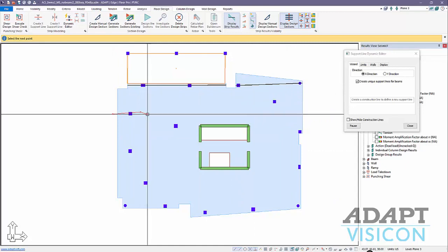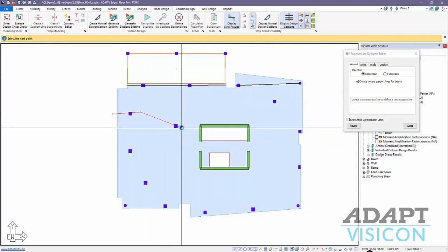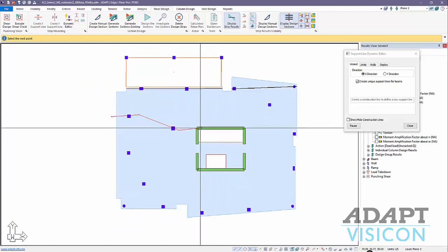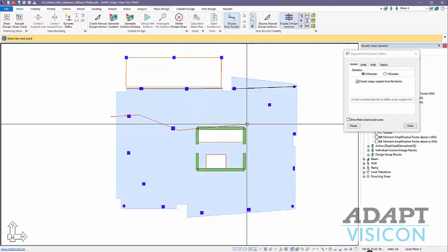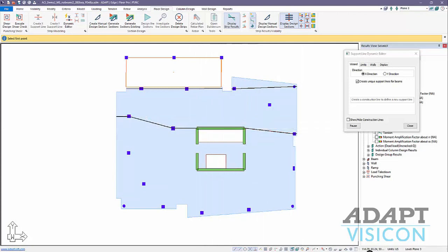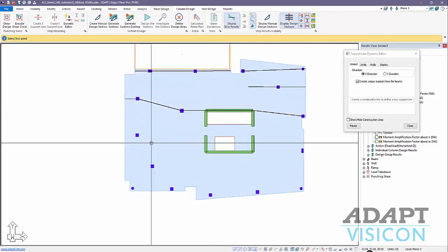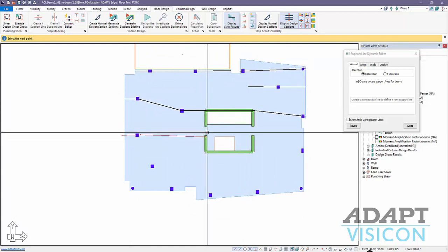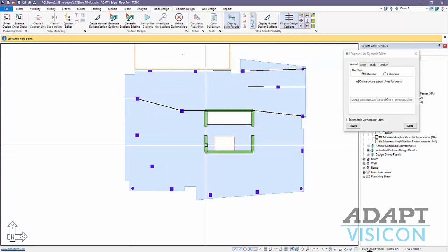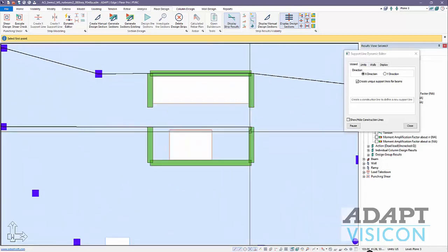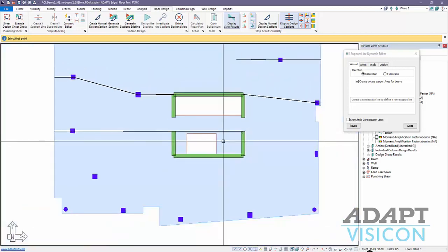Here I can put intermediate click points to change the direction of the construction line. If I click on the endpoints or near the endpoints of walls, it will scan that and pick up the 2 endpoints of walls, like so. I'm going to go ahead and just add one at that location. If I click near the endpoint for a perpendicular wall or a wall in the opposite direction, it will pick up those points also. Now notice what happened here. This ended the line there because I terminated that point.